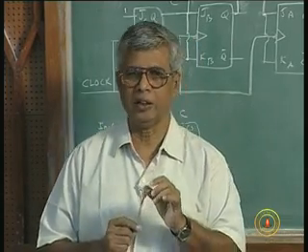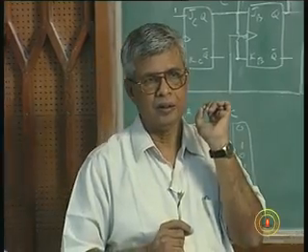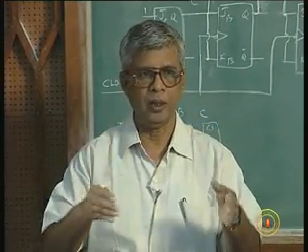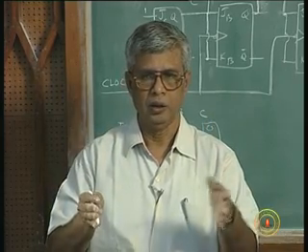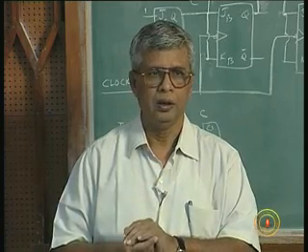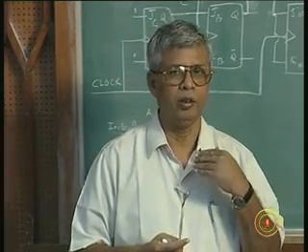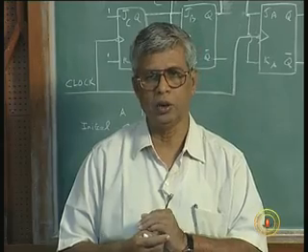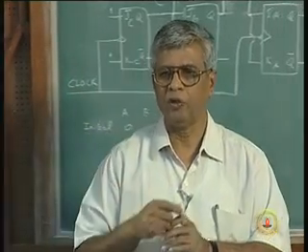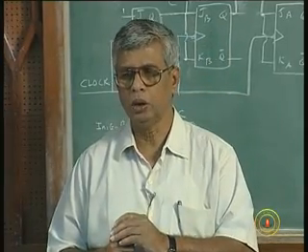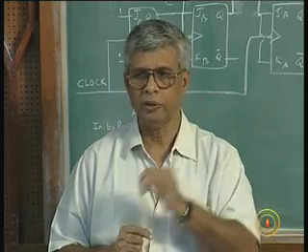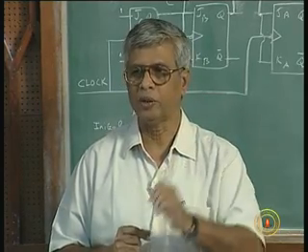in practice you never have words of 1 bit. Usually a word is 4 bits, 8 bits, 16 bits, 32 bits, like that. For example, if you take ASCII code, I said it translates our alphabets and numerals into binary code. I said you get 7 bits for that, and you may have an extra bit for parity, so an 8 bit code. So, I want to store the code corresponding to a particular alphabet. I need 8 bits, 8 flip flops.